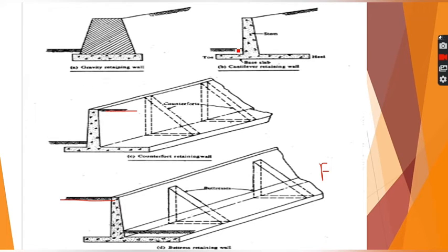We will be doing the design of cantilever and counterfort retaining walls in detail. Buttresses are designed in a similar way as counterfort retaining wall, with the difference that backfill pressure is not acting on the buttresses, as it is quite visible from here.